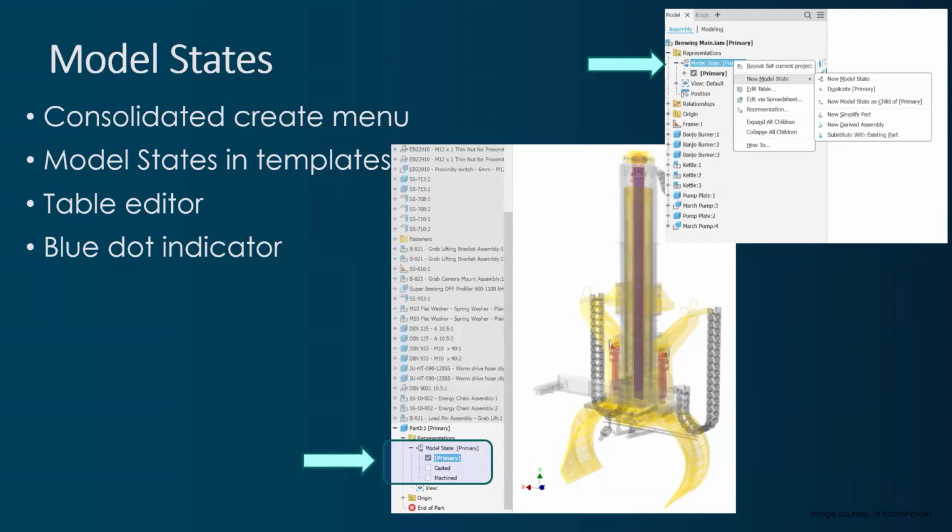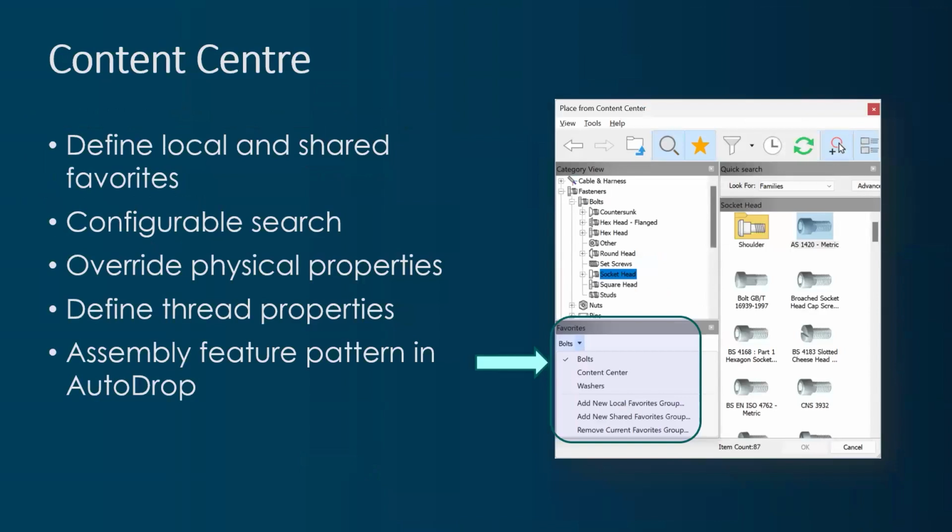But yeah, very, very powerful tool that allows us to set up various iterations and assembly configurations within the file. Basically, the functionality is not unlike how we used to use iParts and iAssemblies, but it's all done within the one unique file. So we don't have multiple members as such. We simply are making a change to the configuration of the actual assembly itself. Quite a nice tool, and I think you'll find that one quite valuable.